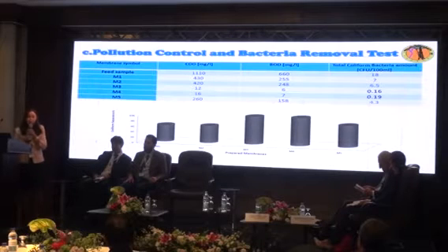Okay, and this is the most important thing. As I said, related to the environmental law, you need to lower your COD and BOD levels in the wastewater. So that's why, as you can see here, by the way, I used for these samples real water from GUPCO fields. For membrane number 3, the COD decreased up to 12.